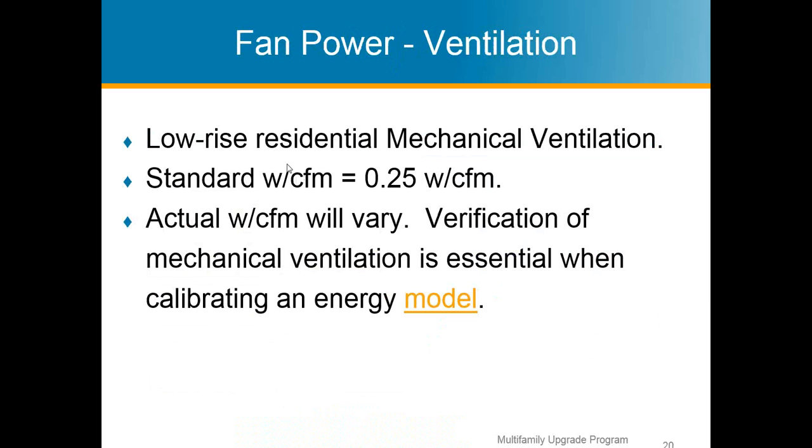So, low-rise residential mechanical ventilation. The standard, we're going to talk a little bit about fans and how fans can affect this calibration. Your standard is 0.25 watts per CFM as a baseline, but your actual watts per CFM may vary significantly.